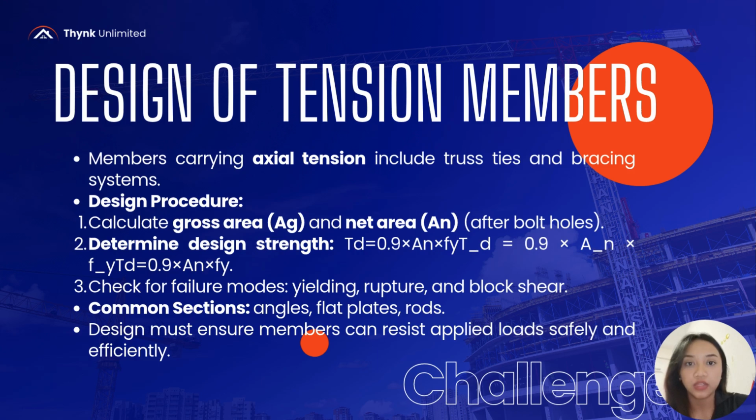Next is design of tension members. Members carrying axial tension include truss ties and bracing systems. These are the design procedure. First, calculate the gross area and net area after bolt holes. Second, determine the design strength. These are the equations for the design strength.